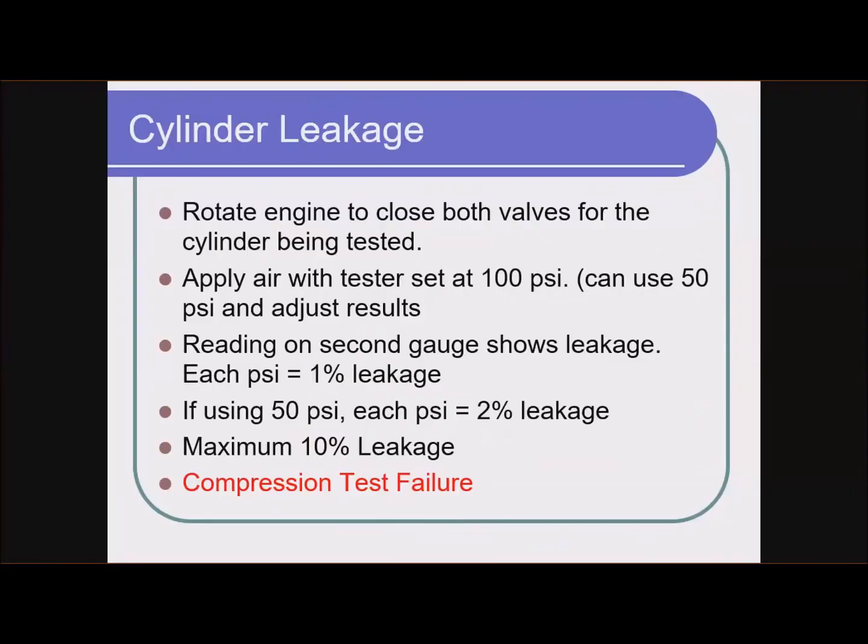How do we do it? Well, first thing we do is we look at the bottom here in red. The question is, why would we do a cylinder leakage test? The answer is compression test failure. And I know I discussed this in the shop, but let's just talk about it again for a minute. A cylinder leakage test can be time consuming.